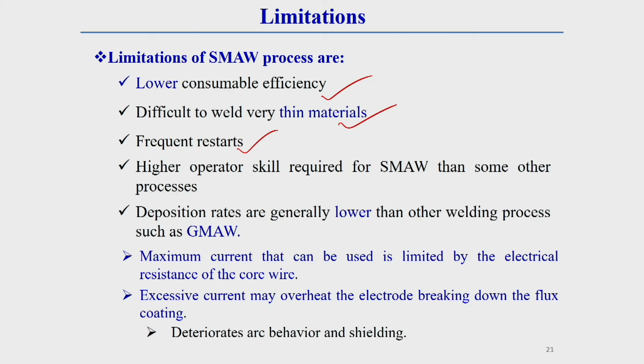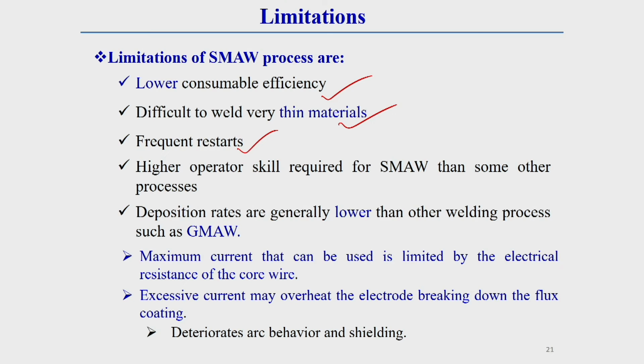And here one thing you should keep in mind, here generally operator skill should be comparatively better than other welding processes. So higher operator skill is required in SMAW process than other welding processes, because here so many techniques, so many things are required to control, what I have already told you. Another thing you should keep in mind, deposition rates are lower than other welding processes like GMAW, that is gas metal arc welding or MIG welding technique.